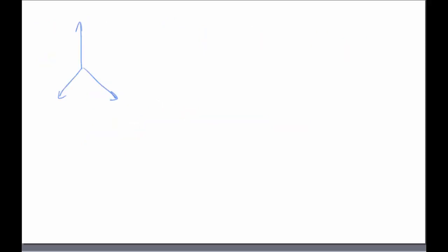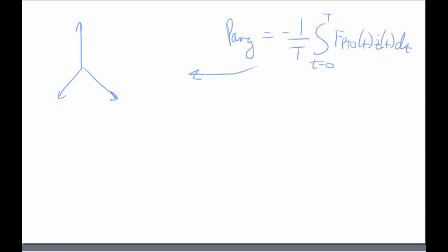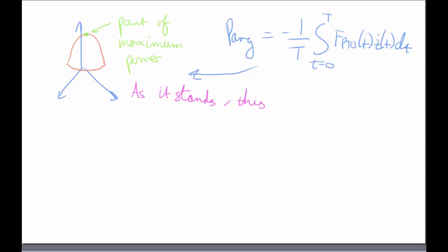So as I was saying there, this isn't based off the conventional MPC, it's based off this, where the cost function is based on the average power absorbed. Where if I plot this in terms of the FPTO force, you'll get this convex function, which is plotted as this graph. And I'm trying to find the maximum point here, but unfortunately, if you use AMPL or IPOPT, they'll try and find the minimum points here, and then it'll be basically a non-convex equation.